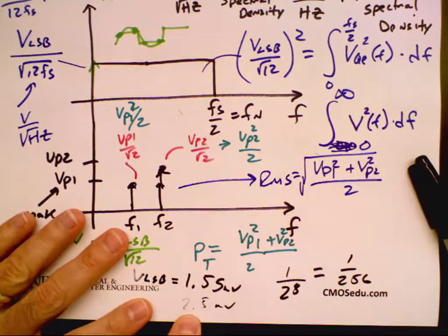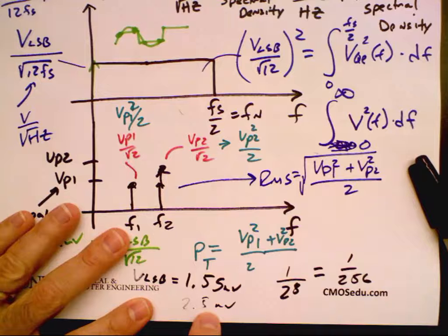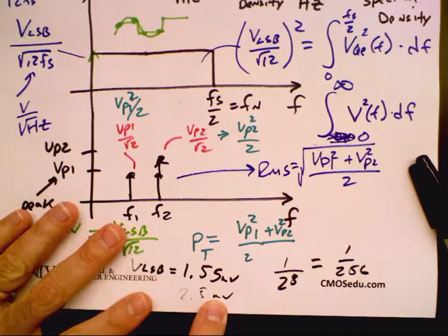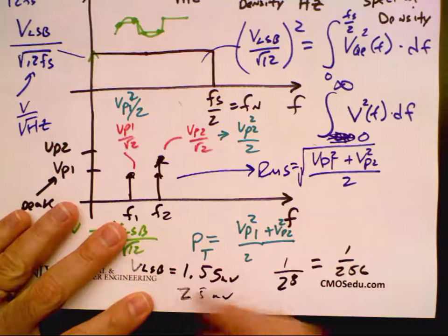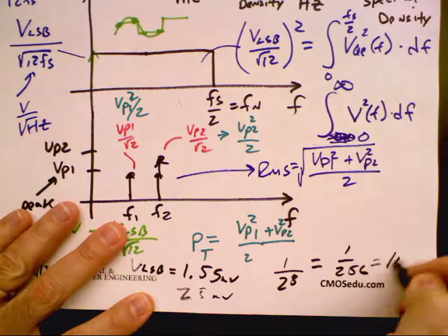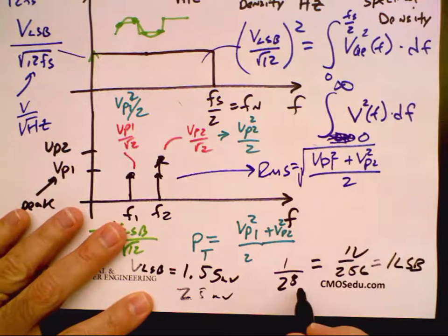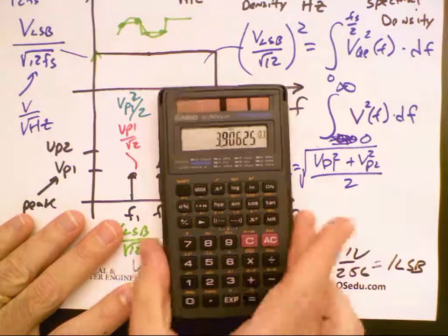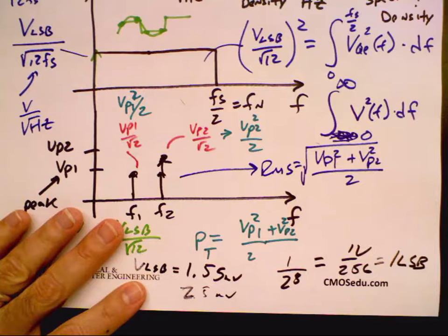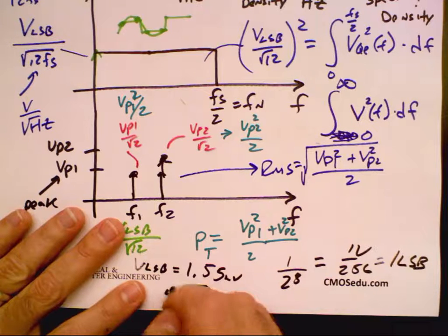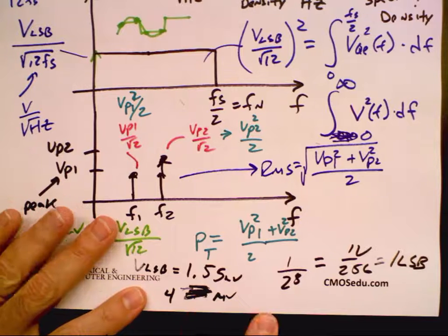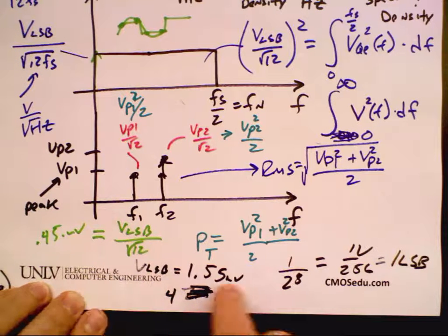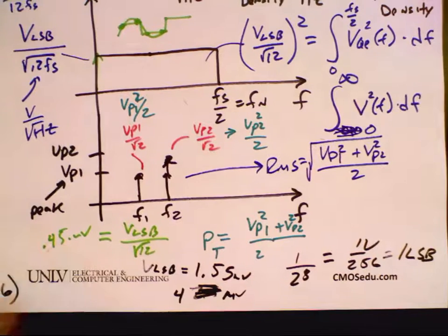And you can see, well, wait a sec, if I used a wider spectrum, I'm going to get closer to this. Did I lose anybody there? Okay, so any questions on how I calculated 1 LSB? It's 1 volt over 2 to the 8th. So that's 1 divided by 256. Oh, it's 3.9, sorry. Roughly 4. That's why everybody looked. So it's roughly 4. What I did with looking at the spectrum and adding everything up was I said the RMS value of the spectrum, and how did I do that again?